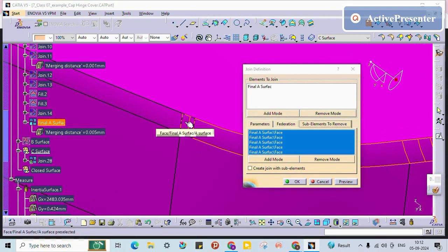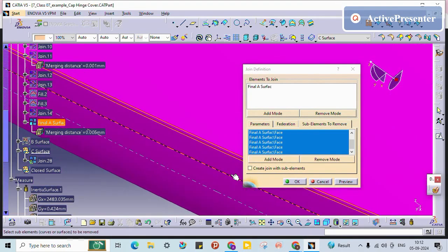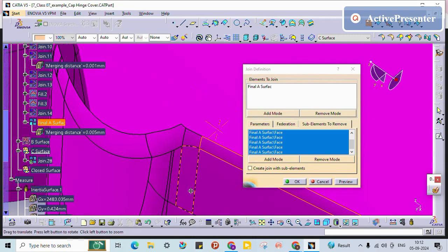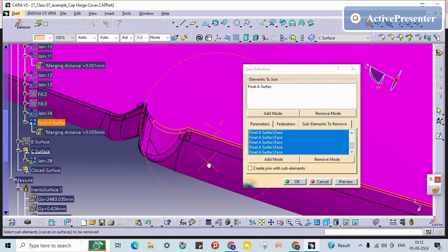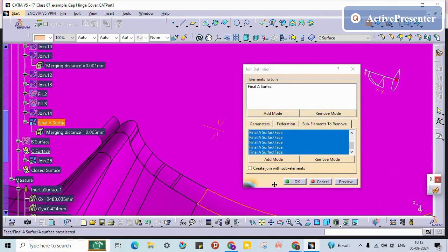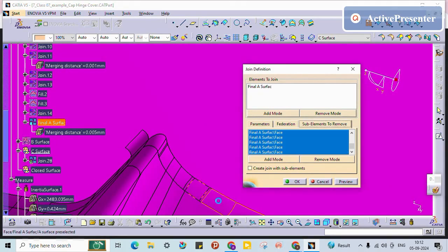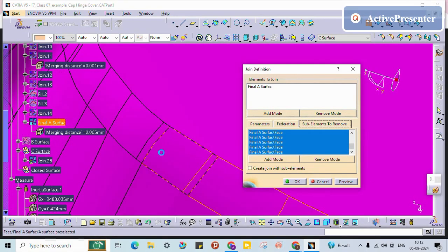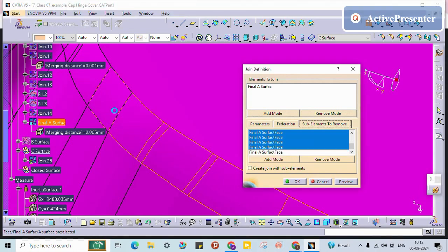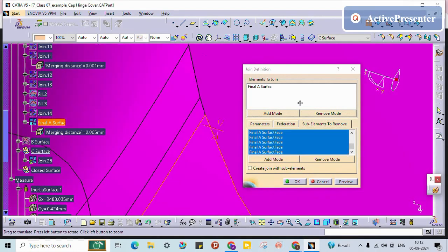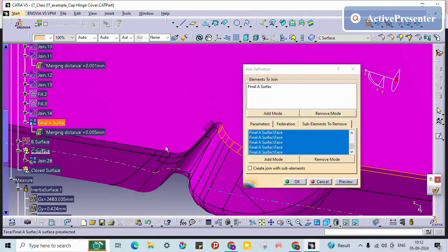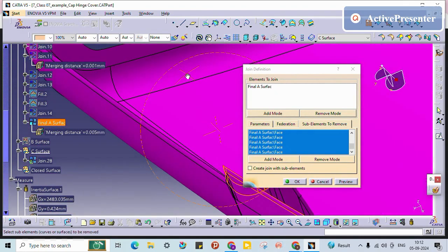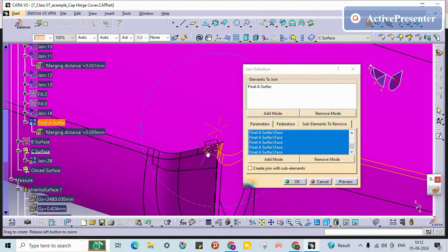So as I told earlier, this part is taken from 3D CAD. That is why it is this complex at the corners. Whenever you get a surface, it won't be that complex at the corners. Because it is a critical area, it will have the C surface as well as your parting line.